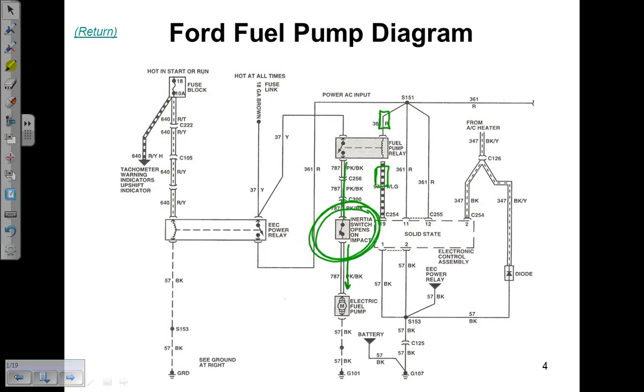But look for those. For example, a Hyundai that I looked at not too long ago, one of the garages I worked for, it was a no start, it was a body shop. It was a Hyundai Santa Fe, and it had a subframe put in it, so all undercar damage. And the car wouldn't start. Now, unfortunately on this car, checking fuel pressure was not easy to do. There was no Schrader valve on the rail, so I couldn't adapt the pressure gauge easily. The car wouldn't start, had good spark, shoot some carb clean in the intake, fires right up. So I know it's a fuel issue. I got to check my fuel pressure, but I can't do it. I don't have the right adapters.